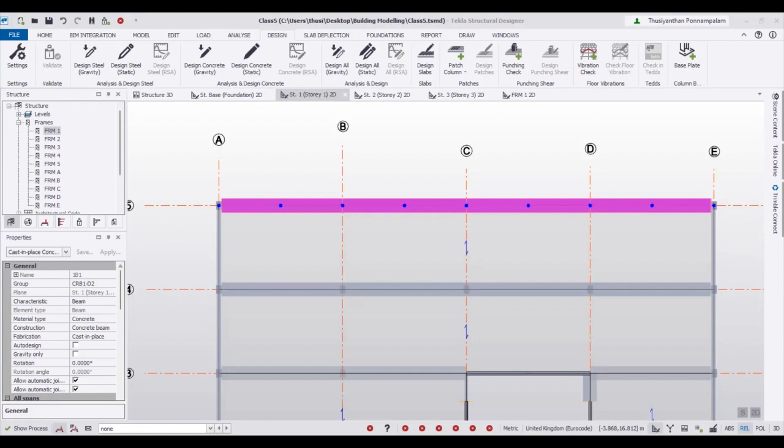So the second thing is the beam schedule, the bar bending schedule, right? In the mark you can see later on. See each bar type, how much quantity you want, right? It's already calculated for you. So you don't need to go back and do all the bar bending schedule.